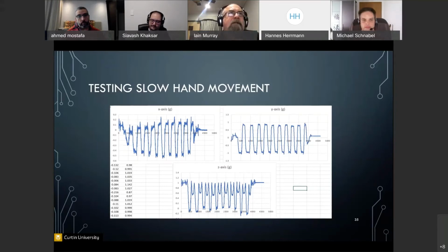The other part, again, to take from this is the need for signal conditioning, the removal of noise. In IMUs, that's really difficult. Part of the noise is drift, but in a lot of other types of sensors, you're reading either harmonics, which is a multiple of the frequency that you would normally get, or there are stray elements like electromagnetic radiation being induced into it, and you want to find out only the data you need, not the noise induced. So you need to have a method of working out what is actual data, what is noise, and how can I subtract that noise from the sensor. Otherwise, you'll be collecting lots and lots of data which has absolutely no meaning. So linearization and noise and signal filtering are critical components, whatever sensor you're selecting.